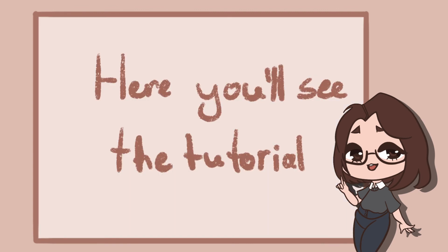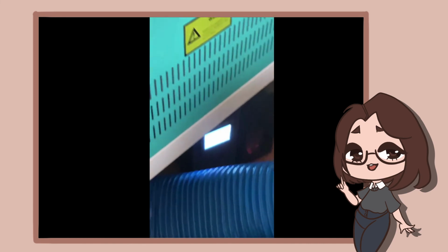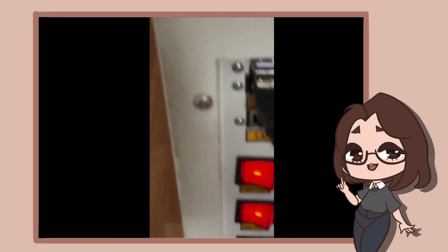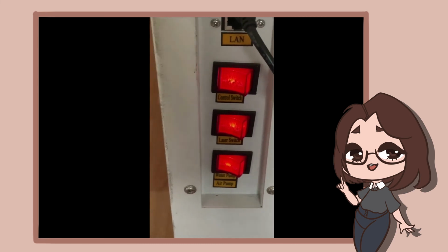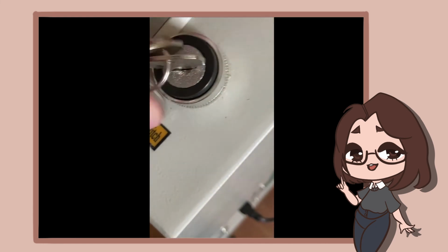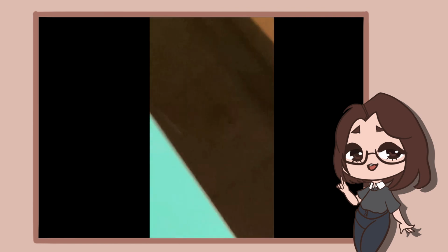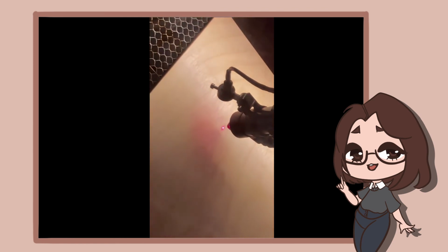Now that we finished with all the work we needed to do with the programs, let's go to the laser machine. First of all, we need to turn on the water chiller, then we go and turn on the high voltage block BVN model. Then we turn on these switches. If the middle one isn't turning red, turn on the key. Now you can see that the laser is working. Also, you need to turn on the hood.